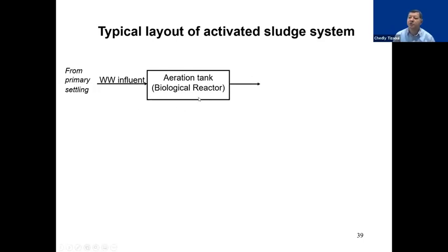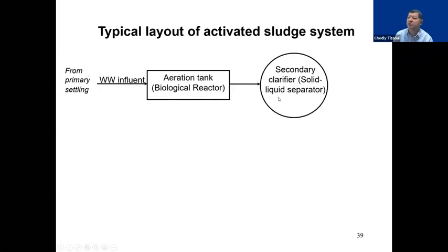In here, you have a suspension of microorganisms where the influent gets into contact with them. That suspension is maintained by a supply of air, using diffusers at the bottom of the reactor or using high mixing by shear force due to a turbine at the top of the reactor.